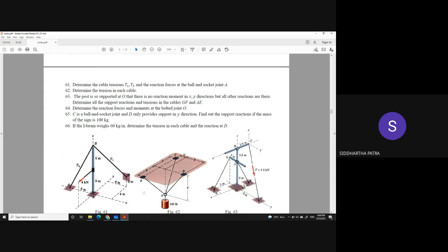Okay, so you have to solve for 5 unknowns from what? 6 equations of equilibrium. So you can get the equivalent force system about one of the points, and because Rx, Ry, and Rz are passing through A, maybe A is a convenient point for getting the equivalent force system. So you can get your equivalent force system about point A, no problem in that. Let T1 and T2 be unknowns. Let Rx, Ry, and Rz be unknown.